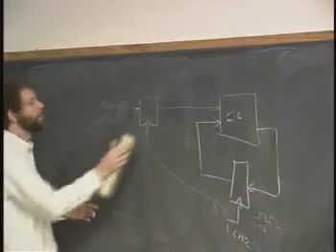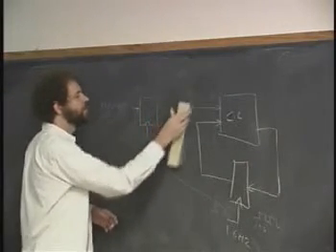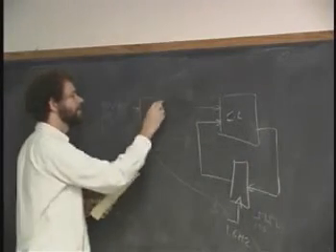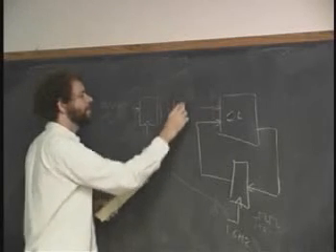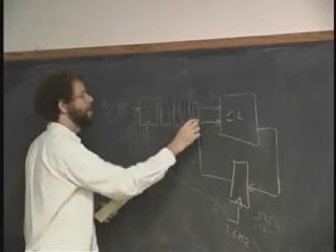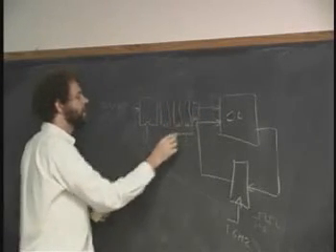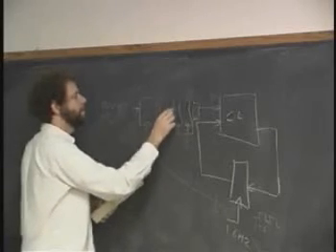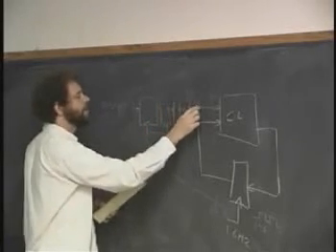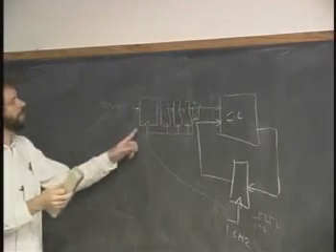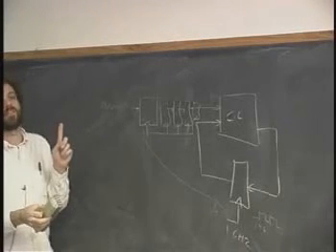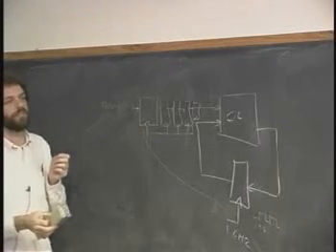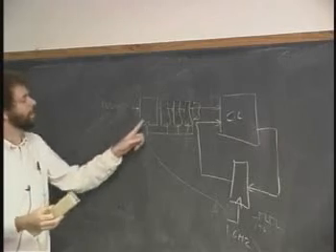Some kind of buffer. What if I were to put 100 flip-flops in a row here? In other words, make an assembly line, or what we call a pipeline, of flip-flops, all clocked by the same clock. Now, if you remember, the probability of this thing still being metastable after 1 billionth of a second is not sufficient, right? We have to wait 100.